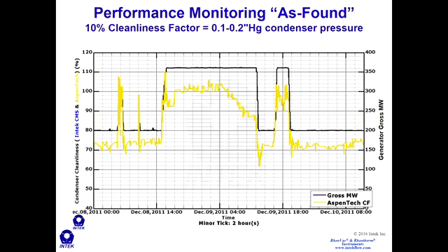And I told him, well, before I give my verdict on what's causing this, let me compare the test grade measurements to the original equipment that's being used to calculate this in AspenTech. This AspenTech is their historian that's being used to calculate this performance parameter. So they're using the station equipment, installed back in the 1970s or 80s, to get this number here. And I said, well, let's take a look at the test grade measurements.